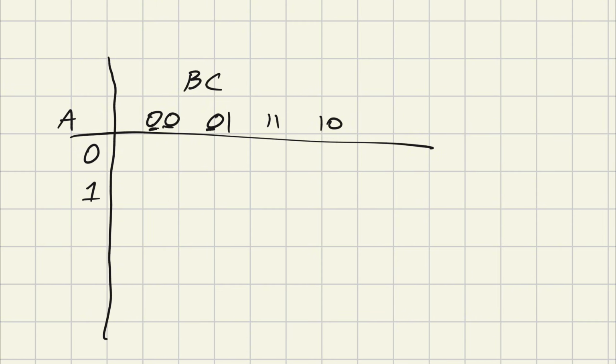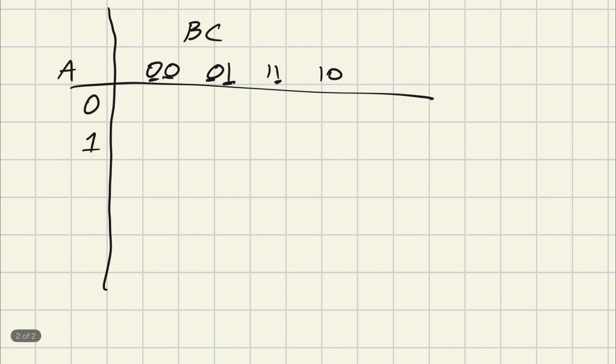And then over here, C is not changed, but B has changed. That's how you know to draw your K-map. That's the correct method. Or you can just memorize this. This is common for a 3-variable K-map or 2-variable K-map or 4-variable K-map. So then we can start plotting our minterms.